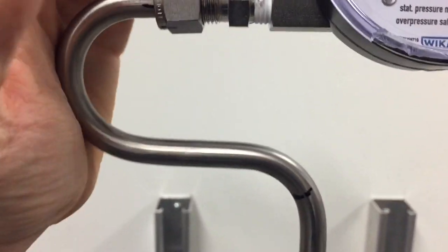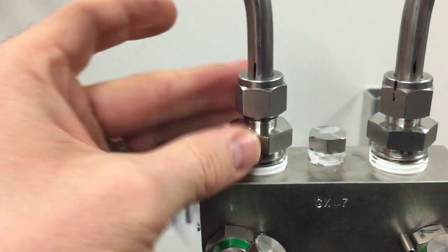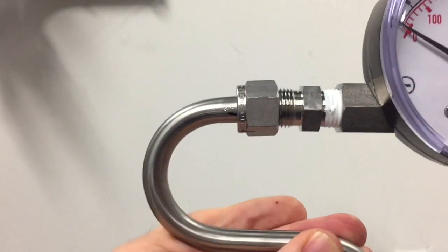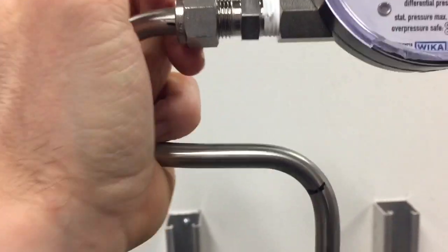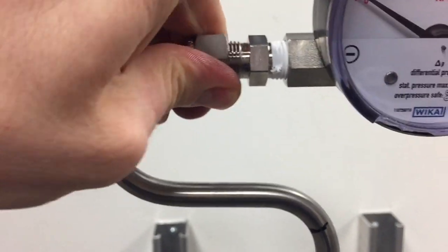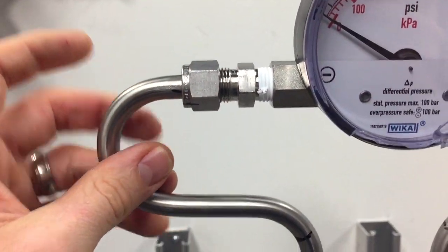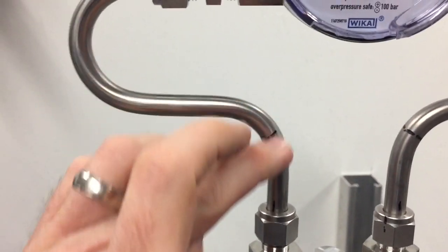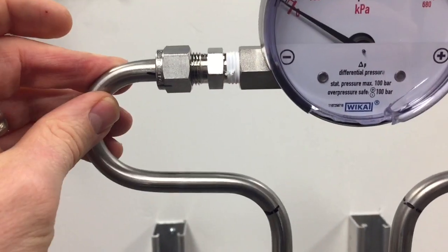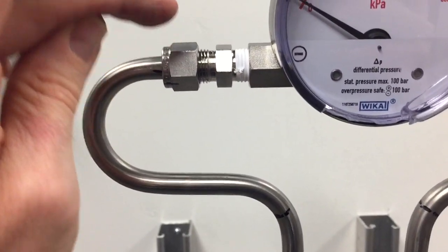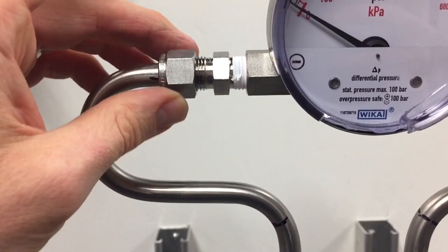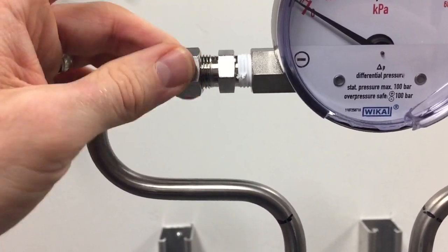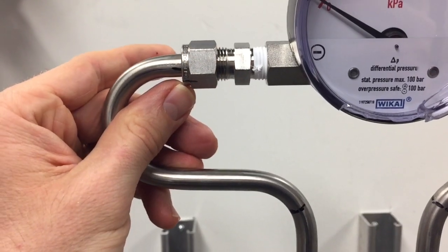If you can't, you may have to loosen a nut off maybe down here, so then you have some more wiggle room over here, and you might have to wiggle the fitting. And there, now that I was able to wiggle it, I was able to get a few threads started. As long as you have a few threads started, then you can use your wrench. If you do not, you will wreck the fitting, wreck the nut, and you'll have to completely redo this piece here, because you have to cut the nut off and all of that. So this is very important. Avoid cross threading your fittings. The best way to do that is to make sure you can get it on with your fingers before you start using a wrench.